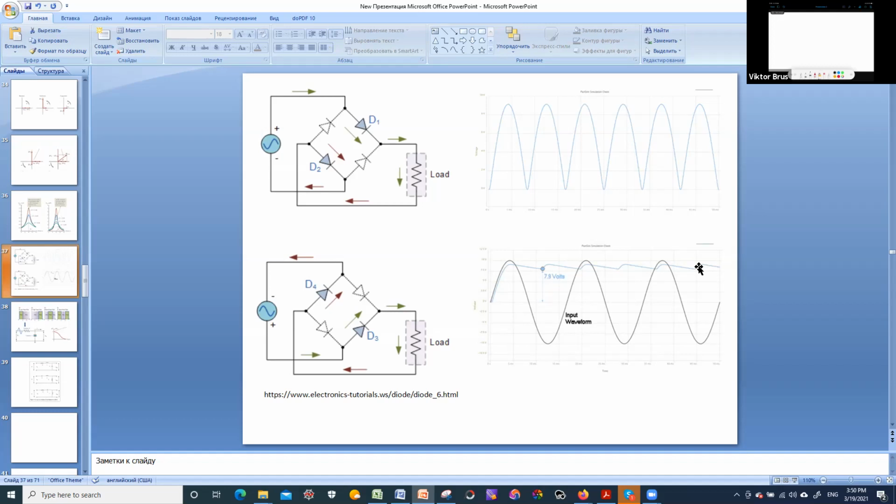These components, transformer, rectifying bridge, and RC or RLC high and low pass filters, are always present there, because if you want to get high quality DC current as output without any parasitic signals from low and high frequencies, it is necessary to apply all these three components, realized in different ways.